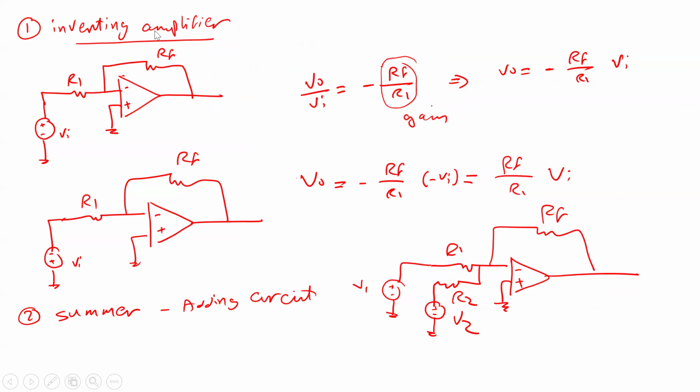I started with the first application here, the inverting amplifier, and this is how you should connect the circuit. You need the feedback this way from the output to the input. This input, the non-inverting input, you connect it to ground, you put here R1 and the input this way. And for this circuit, you need to memorize these circuits. I will tell you why.